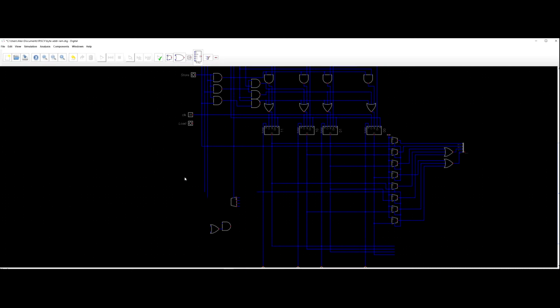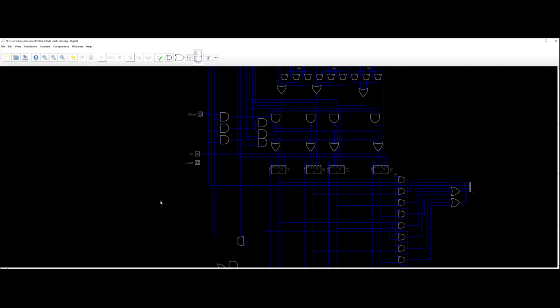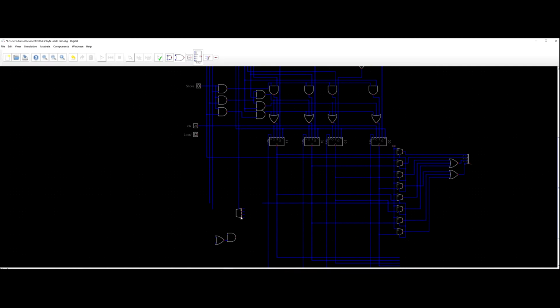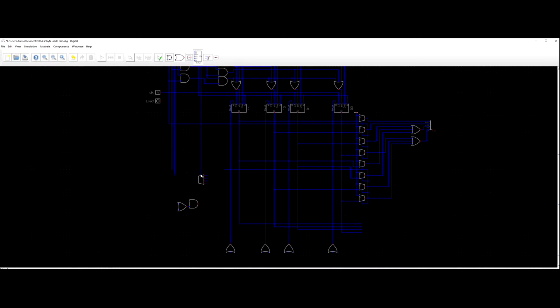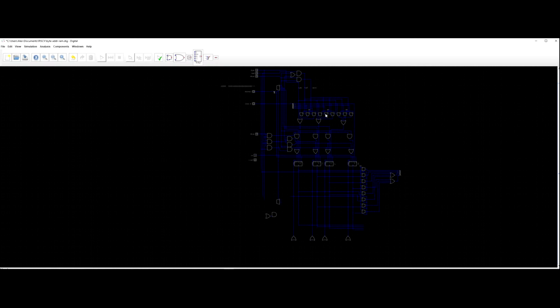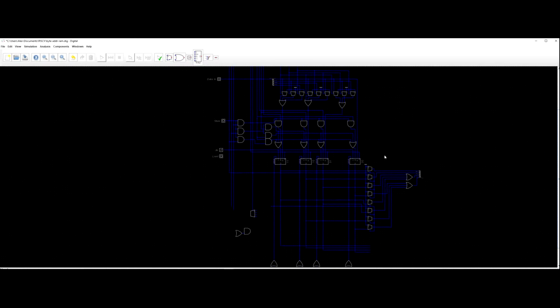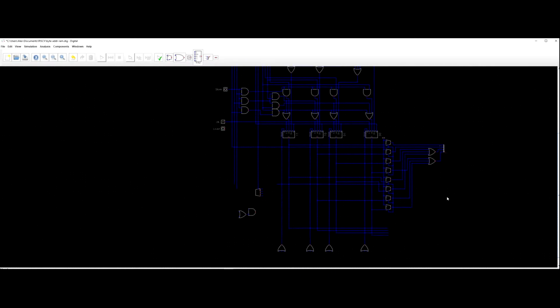Can't you take the control signals after the decode and use them in the muxes at the bottom? Right, but then you see how many more muxes I'm using? I would need more muxes. I'm using 9 muxes here to control handling all the input splitting. Why can't I use the same amount of muxes to handle the output splitting? I can throw more muxes at the problem, don't get me wrong, I just don't want to. Even though they're in parallel, I'm just not going to slow anything down. It's just extra complexity that doesn't need to be there.